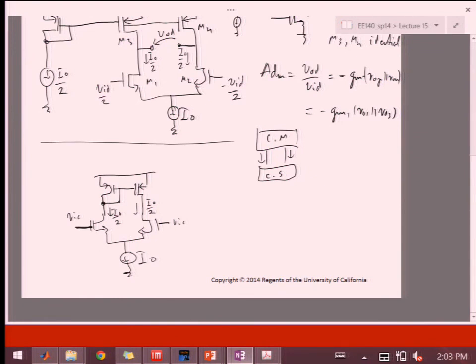I'm not going to split apart the whole circuit, but I'm going to be able to say that if I have a differential voltage here and a negative differential here, I can assume this is grounded. And if it's grounded, then I can do superposition, because in this case, I only have this one output, VO. I can do superposition from this input to this output while this guy is grounded. And I can do the other thing vice versa, right?